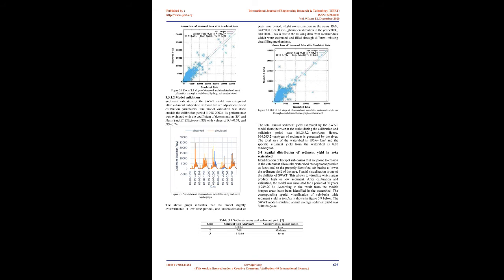3.3.1 Model Calibration and Validation for Sediment. 3.3.1.1 Model Calibration. SWAT model was calibrated for daily sediment yield after calibration and validation of stream flow at the outlet of Soke River watershed. The measured sediment data was generated from the prepared sediment rating curve. The measured and simulated sediment were compared for the calibration period, 1992 to 1997, in SWAT_CUP. The SWAT model performance was evaluated through coefficient of determination, R2, and Nash-Sutcliffe efficiency, NSE, with a result of R2 equals 0.79, and NS equals 0.78.